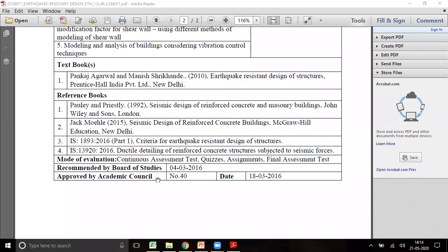So detailing is nothing but, of course, at the joints the shear force will be maximum. For that shear force we will be providing the stirrups. Okay, so for that, shear forces will be used to calculate the stirrups and their spacing. Okay, and at the center or mid span, your shear will be very less, so we will be providing the nominal spacing. Okay, whatever the maximum spacing allowed, that will be provided based on IS 456.